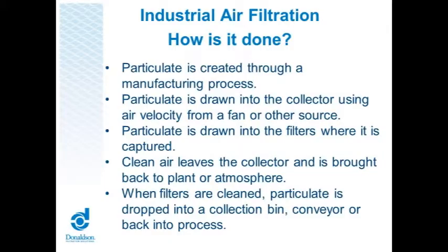Well, we create that dust through the process, whatever the manufacturing might be. We then create a negative off of the fan, which then pulls the dust from its source through the ductwork to the collector itself, and then it is moved or cleaned off the filters, or whatever we're using to capture the dust, and put into a container that you can dispose of or put back into your process. If it's a precious metal or something like that you want to keep, we'll put it back in the process and you can reuse it and save that money.